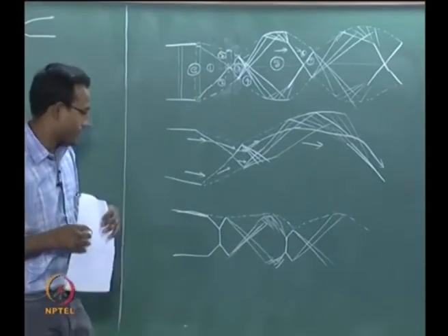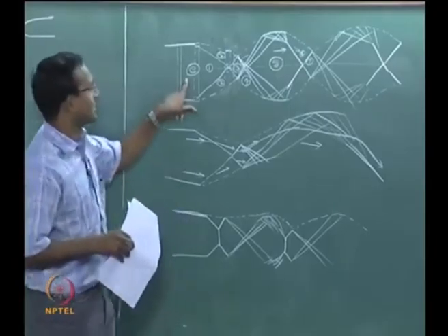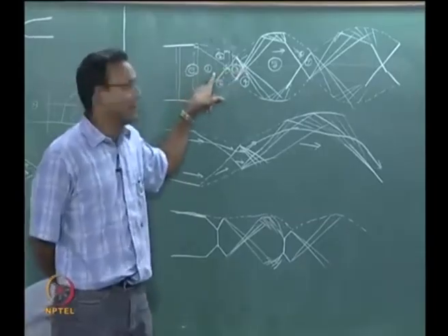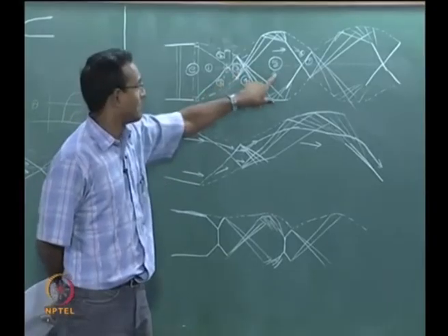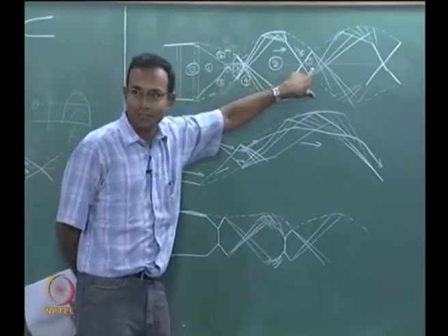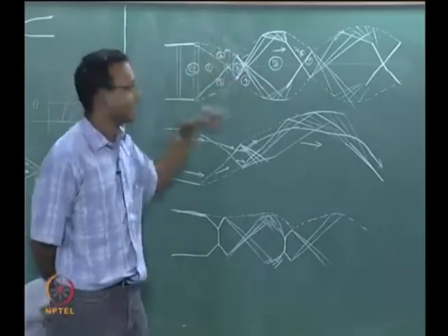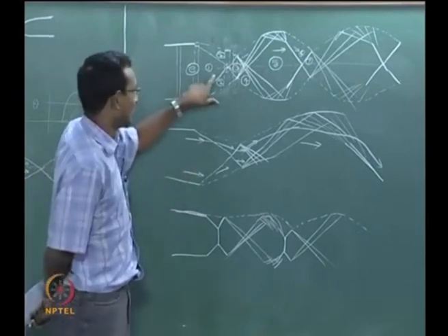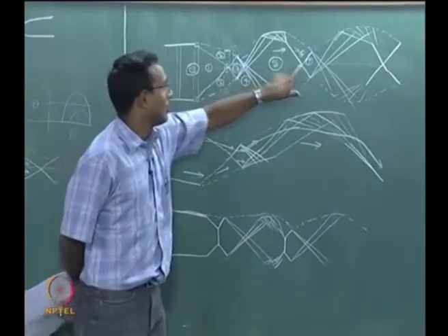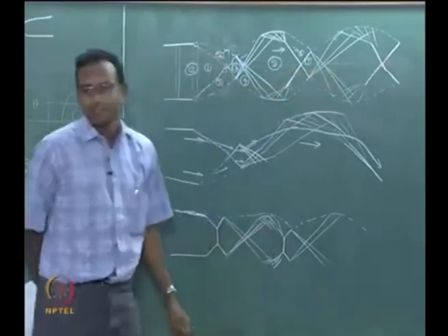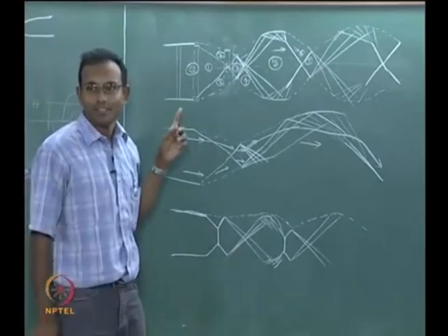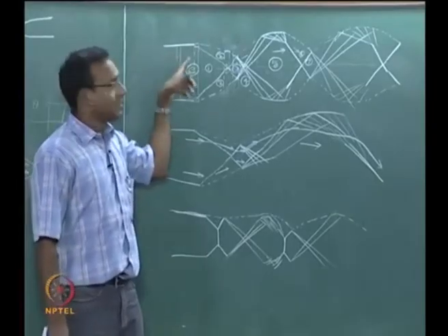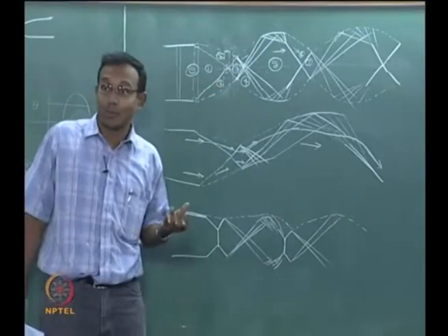If you think about the temperature of the gas along the center line, I will go back to this picture, it is nice. If I think about the temperature of the gas along the center line, 1 is high Mach number, 3 is low Mach number, 5 is high Mach number, 7 is low Mach number, right, expansion versus shock. So I can tell if it is high Mach number, it is low temperature. So here it is low temperature, here it is high temperature, low, high, it just keeps oscillating. Okay. What happens because of that? If I have hot gases coming in, the temperature becomes so high here that the gas starts glowing.